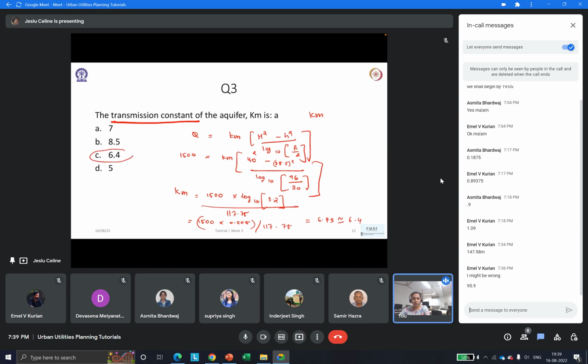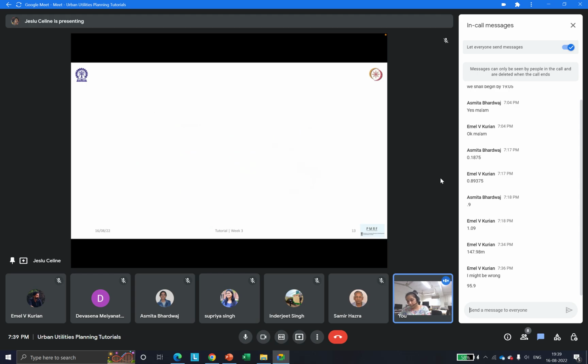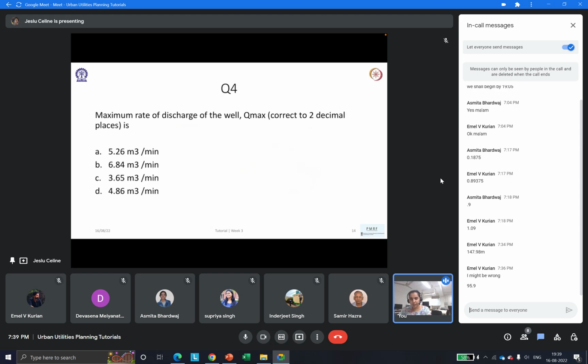So I just went a bit fast in this calculation because it's just direct formula application. You may take a screenshot of this and keep, or the videos will obviously be available to you. We'll proceed to the next question because we have a few more questions to discuss. And with respect to the same question, now we've been asked to find the maximum discharge of the well. So what do we mean by maximum discharge?